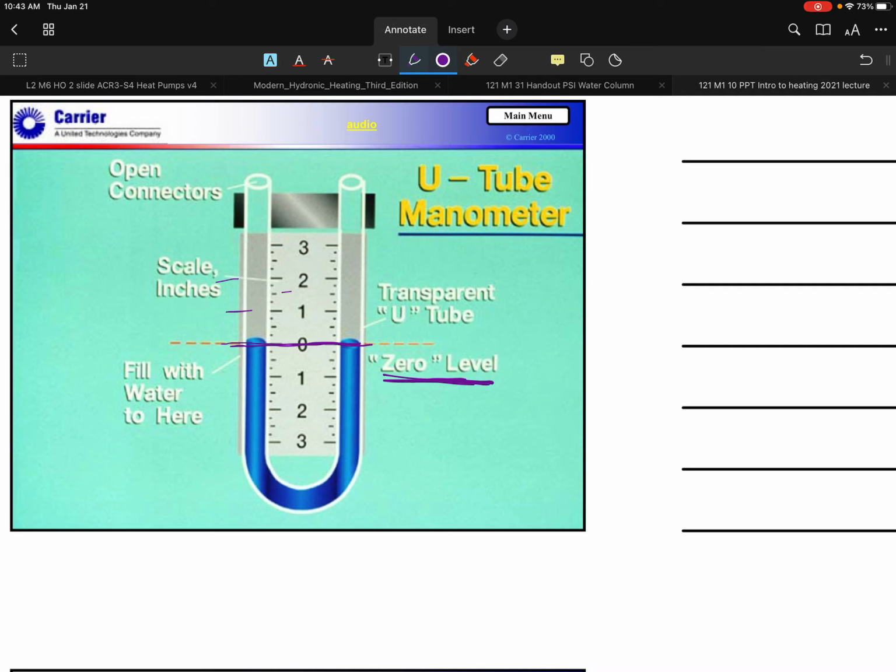We could literally build one of these as a good little activity. Take a 12-inch ruler and use 6 inches as the starting point; 6 inches would become our zero. Then take an 18-inch or 20-inch piece of tubing and wrap it around the ruler, from top to bottom, attached on both sides, and then you just add some water.